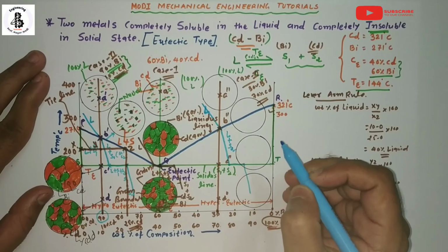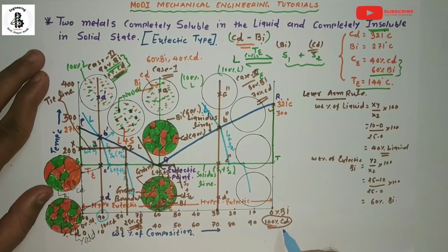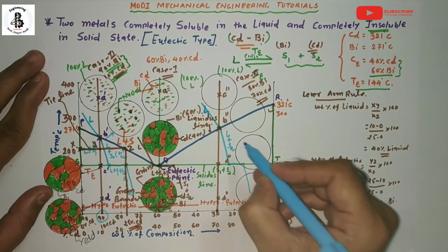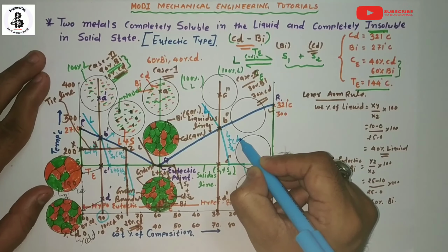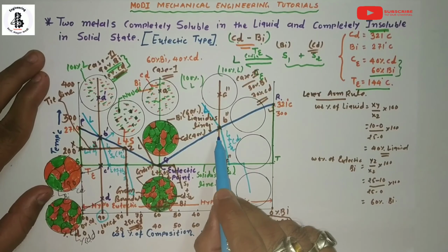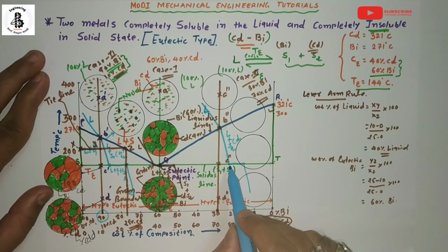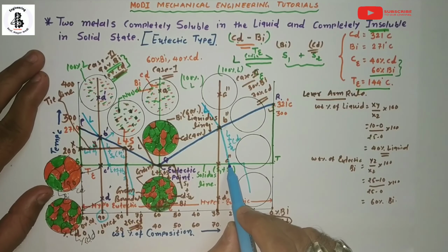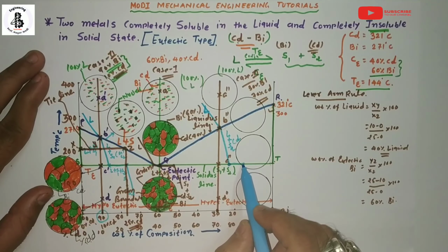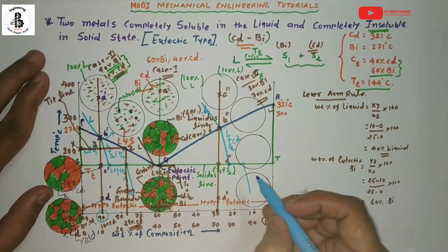Here solid 2 represents the enrichment of the metals. From this side, that will be the enrichment of cadmium, so this S2 acts as cadmium. So in the hypereutectic transformation, cadmium plays a vital role in starting the solidification process. Now as the solidification continues, it touches the eutectic temperature line. At the eutectic temperature line, it is a constant temperature solidification process.